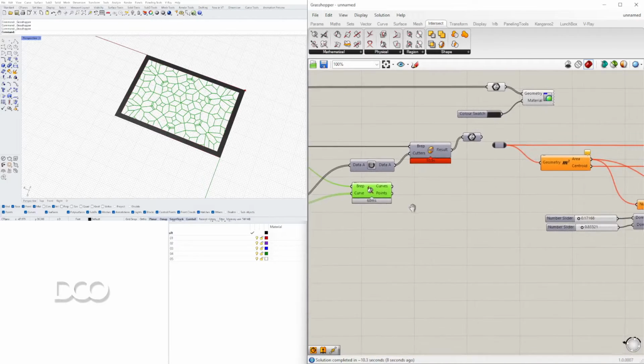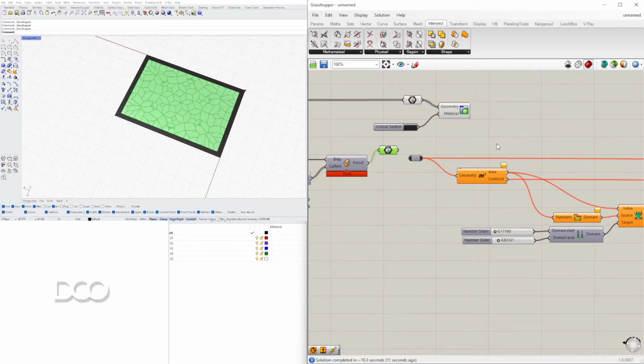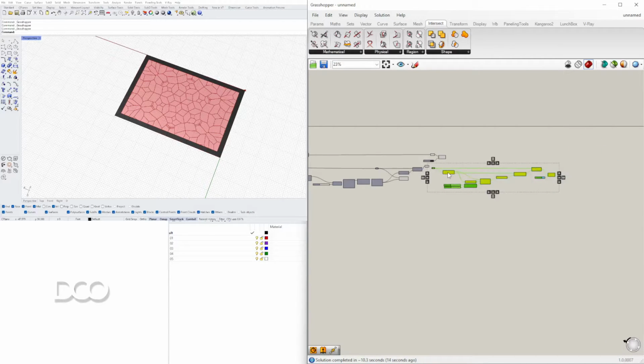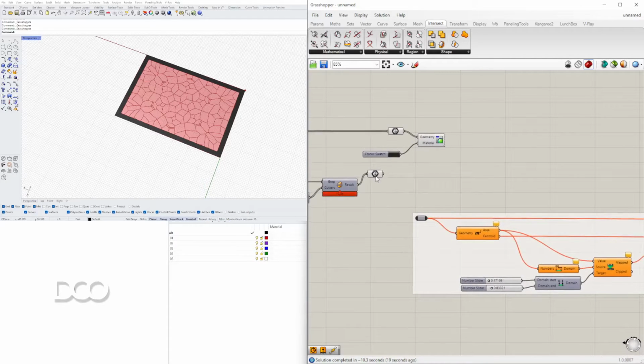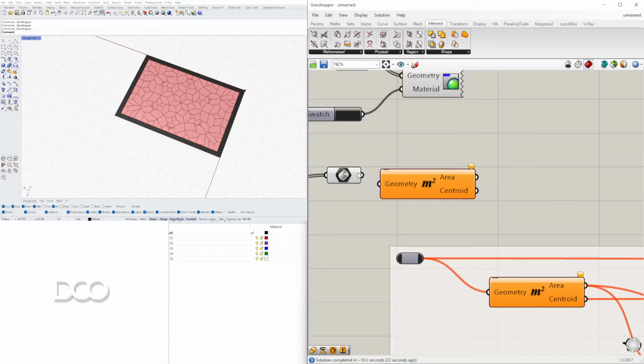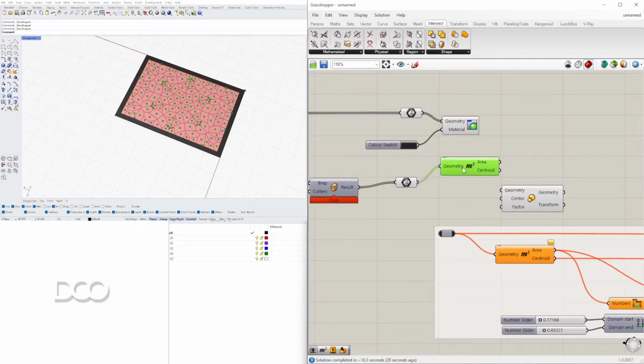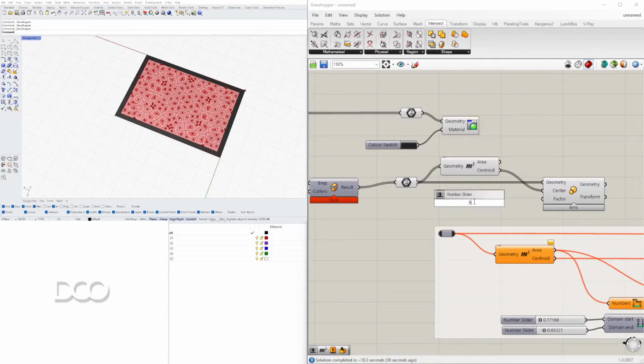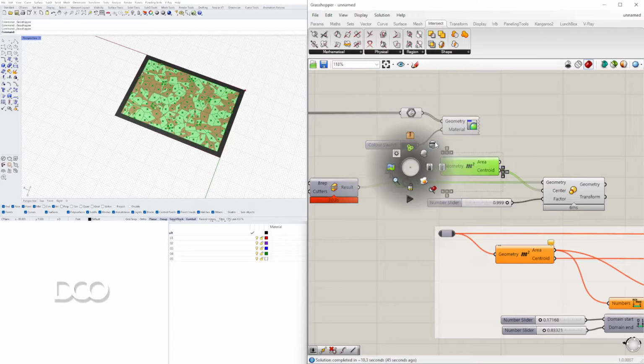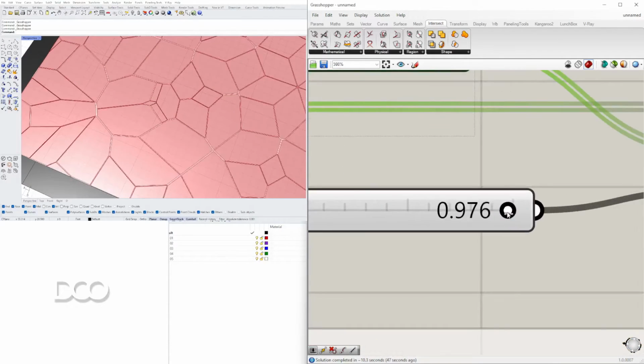Okay. Let's take those, or this brep. I'll group this, move it to the side. Okay, and now here with this one, I'll bring in the area component. So once again, the midpoint. Now we'll be using scale. So I'll plug in the geometry, and we're going to be scaling it relative to each and one of those center points, and just enough that it leaves a gap between everything. So we'll go 0.999, disable the preview on everything else, and now let's move this down a little.